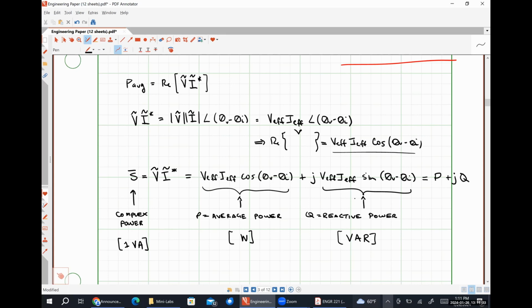So let's talk about what average power represents and what reactive power represents. Okay. Average power is the power that is consumed by a load and is able to be converted into heat. So we call that the energy that's capable of performing work, and it's literally just an energy transformation, right? We're transforming electrical energy into heat energy. We're saying that's what our average power represents. Our reactive power is what's going on with the inductive and capacitive parts of our associated loads.